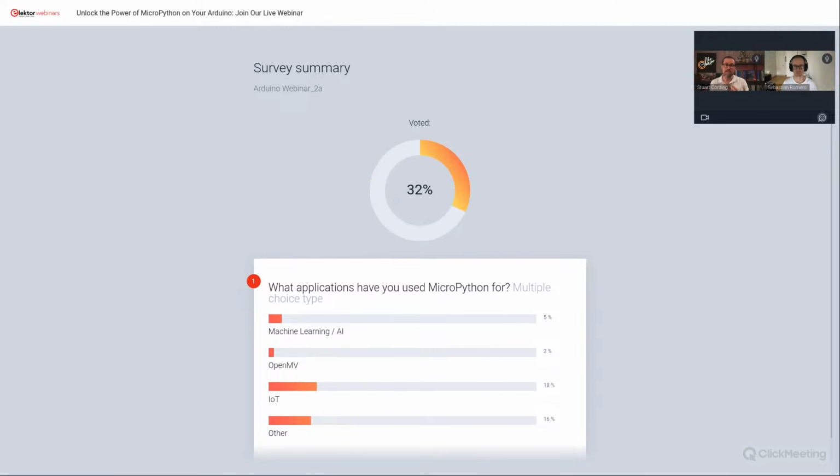But I think one of the things that we see reflected in these results is the fact that MicroPython really is a good platform because of all the libraries that are included for handling IoT and communication type embedded systems applications. One of the advantages generally of MicroPython over just programming in normal C or C++ is the fact that string handling and things like that, manipulating XML files, is much, much easier in Python because it's all sort of integrated into the environment. So against classic bare metal C programming of microcontrollers, MicroPython provides a lot of advantages.